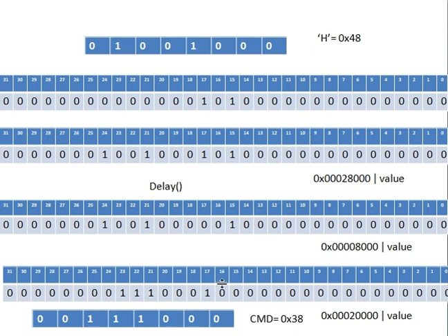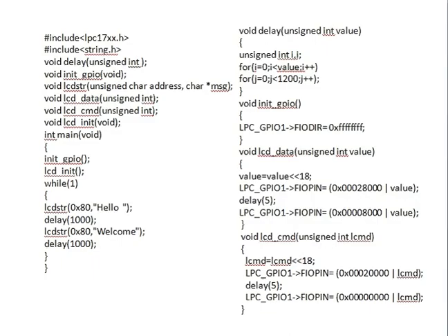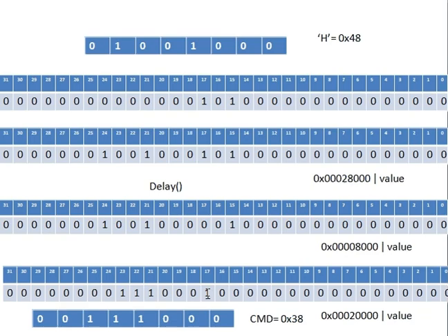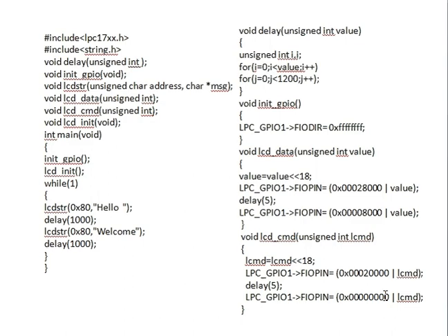Okay, and now this will not enable, because to enable you are supposed to provide a delay. Hence we are using a small delay. We hold this state for a while, then we make pin number 17, that is the enable pin, low. When this pin is made low, you get the information 0. So you have here 0, and with the 0 you pass the data now.